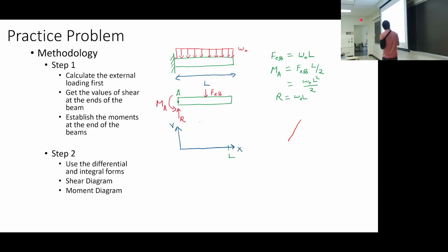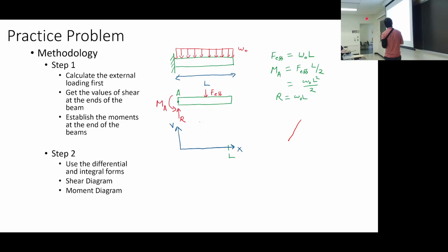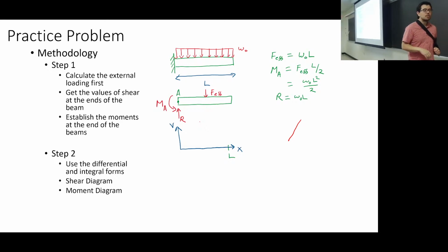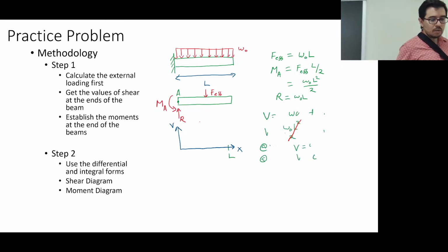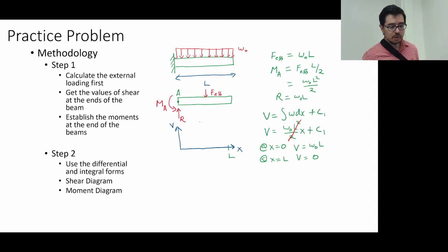Now, if we want to start drawing our shear force, we will want to do an integral. And how do we do this? So we're going to say V is equal to the integral of W dx plus C1. So this is an indefinite integral.